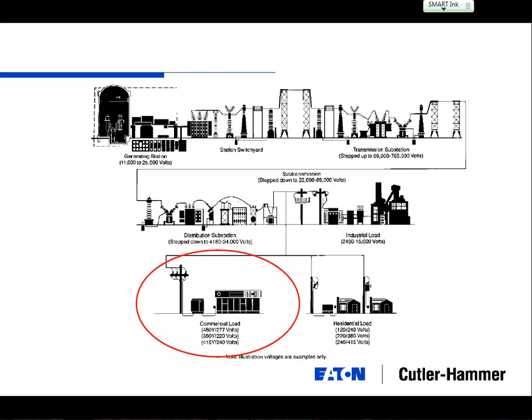Industrial facilities often will take what we call medium voltage right into the facility. Medium voltage, from a manufacturing standpoint, runs from 1,000 volts to 35,000 volts. There are motors that may be 5 kV and some are 15 kV that can be powered directly off this. Anything above 35,000 volts is typically considered a transmission type voltage.